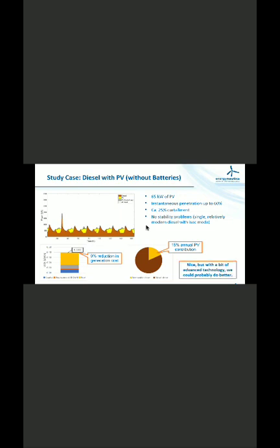So we believe if we add more, it is possible. That's what we did. 360 kW PV with a 1 megawatt hour lithium ion battery. Still, there's a 25% curtailment. You can see this again here, but we can further reduce the generation cost, in total by 25%, and have a 75% annual PV contribution. So this example shows it very nicely, especially during the day, that you can completely replace the diesel and therefore have a really high share of PV and is even economically interesting.